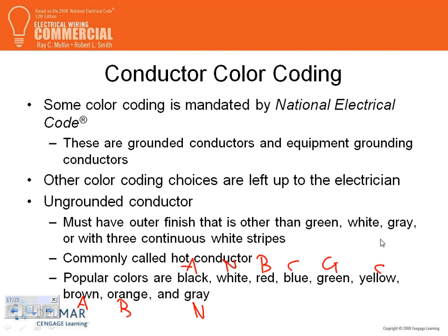Based on voltage, 277 is brown, orange, yellow. The 480 is yellow. It'll be 277 on both; this will be 480, 277. You said that you can use the 480 and 277 with the same colors. It's a two-voltage system. Well, if you had two of them in one building, what would you do? That's one system. 480/277 is one system. It's a grounded neutral system.